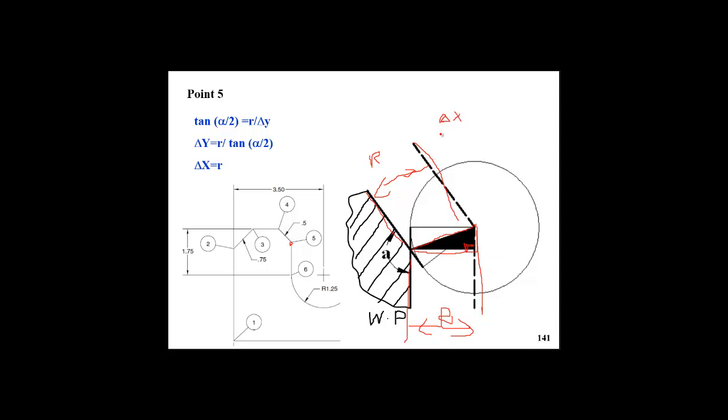One side will equal dx and one side dy. In that case, which side equals dx? That one equals dx, and in that case, dy will directly equal r, the cutter radius. And again, that one has to be calculated using either sine or cosine or tan, whatever the situation. So in that case, if we know that the angle equals half that angle, we can apply tan. Tan of A divided by 2 will equal r divided by dx. In that case we can get dx.